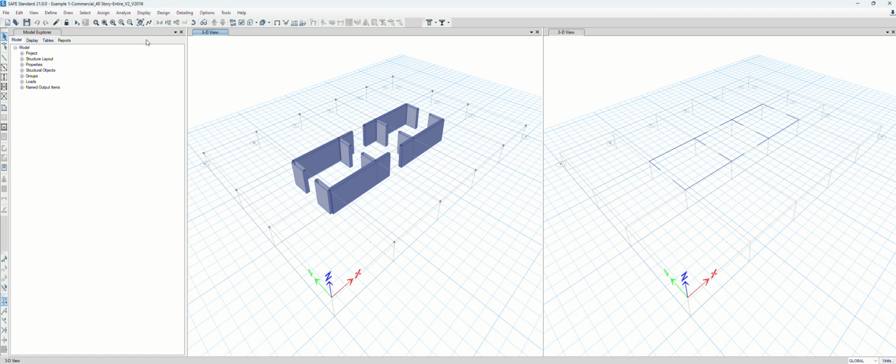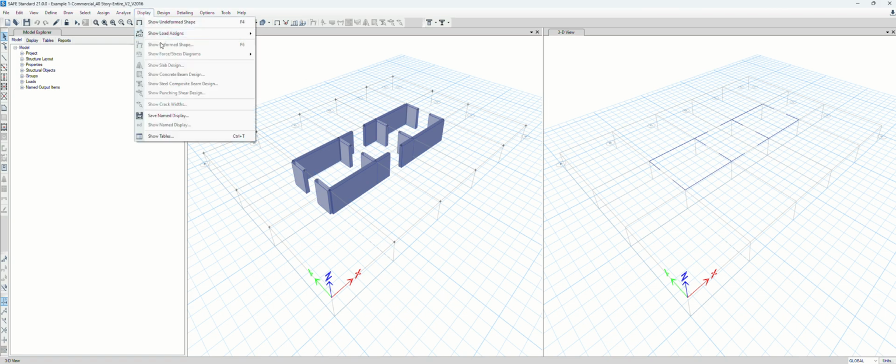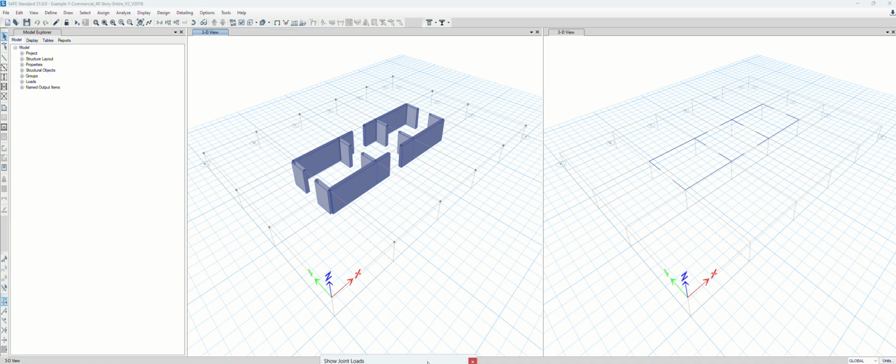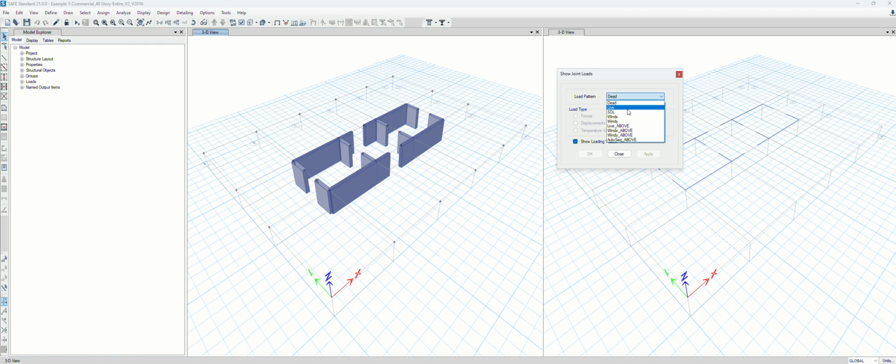So what we're gonna do is similar to the ETABS. Go to display and click show, load, assign, and joint, right? And you see that automatically they set up the load cases, which we're gonna use auto select sequence above. So this is all above load cases, means this is the load case from the ETABS.